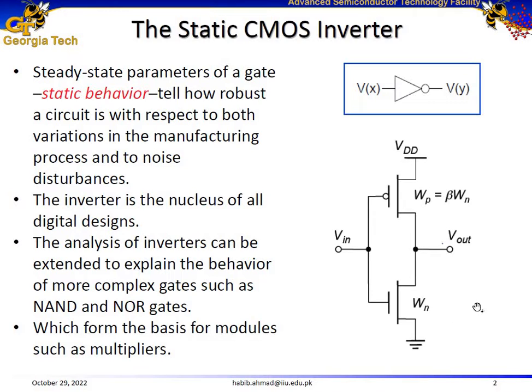And then another key point is that in CMOS, under similar conditions, you might like similar amounts of current to flow through the PMOS and through the NMOS transistors. But we previously discussed, and you might remember the mobility videos for N-type silicon and for P-type silicon. Do you remember the mobility for N-type and P-type silicon?